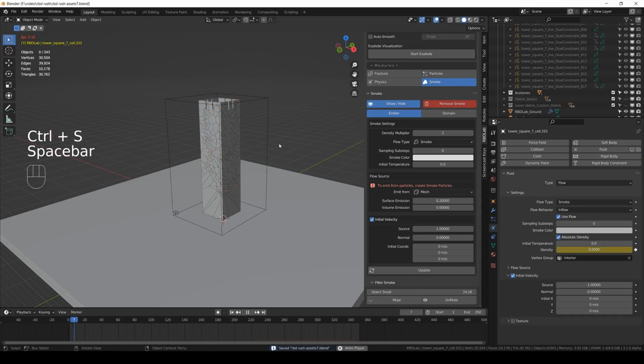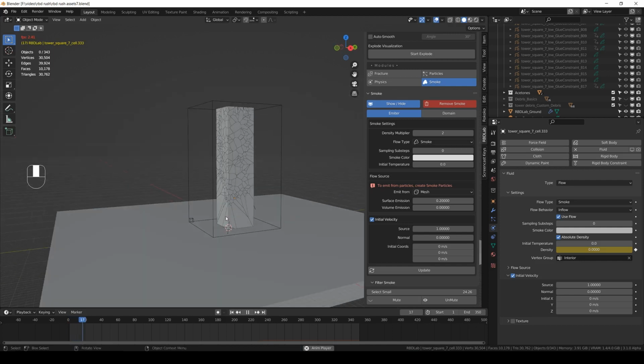In Blender, I suggest that while you are building the setup for the smoke, just leave a very low resolution, like 32 or 64 resolution for the domain, so that it's not going to be so slow and you can actually see what's going on. You're going to increase the resolution just before the rendering. While you are building your scene, you just have to focus on the general dynamics of the smoke, trying to imagine how it will appear with a higher resolution. Just don't care about how it looks now.